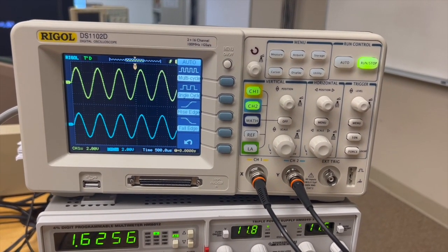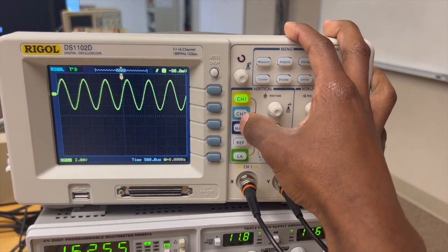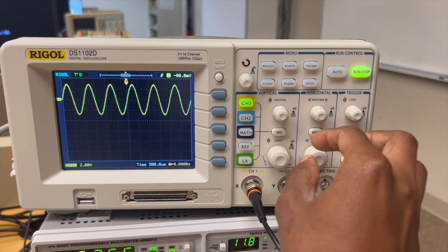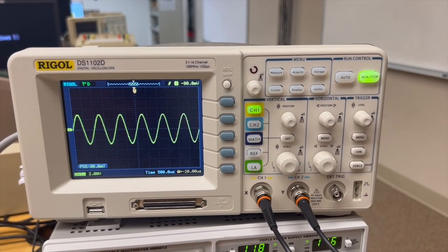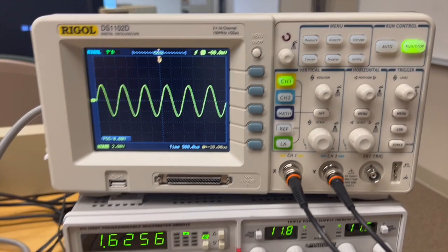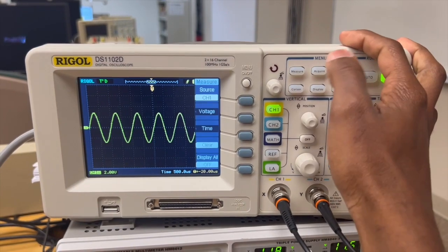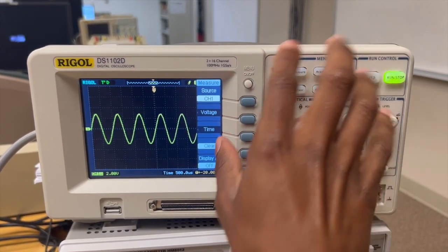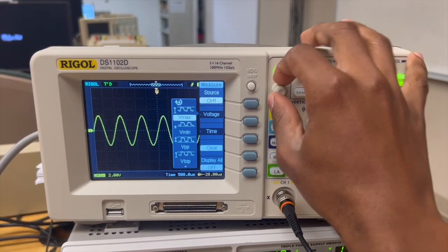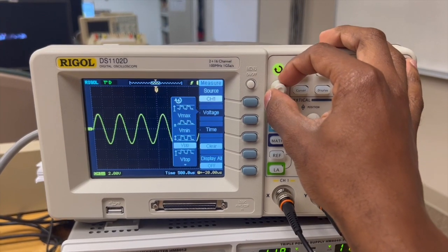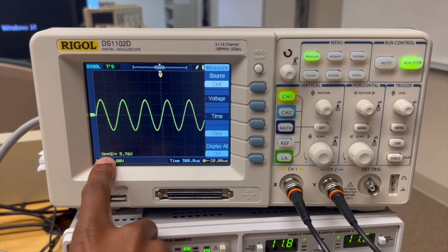First, we're gonna get rid of channel 2 because this is our resistor 2 and we don't need that open right now. So we're gonna press channel 2 twice, and now we're only gonna focus on our voltage source, which is our channel 1. I'm just gonna bring this down just so it looks cleaner and it's even. And now we're gonna look for our voltage peak to peak. We're gonna do that by pressing measure and then scrolling down to voltage. This button pertains to this option. We're gonna click that, and we're gonna scroll down till we see volt peak to peak, which is VPP. I'm gonna press this button in order for it to pop up, and now it's down here.